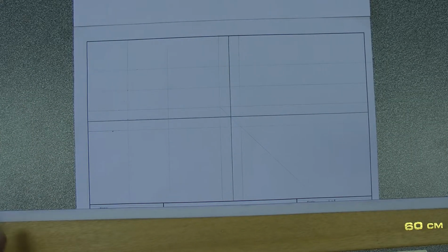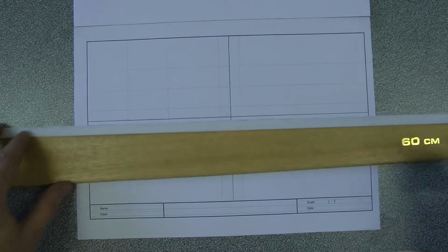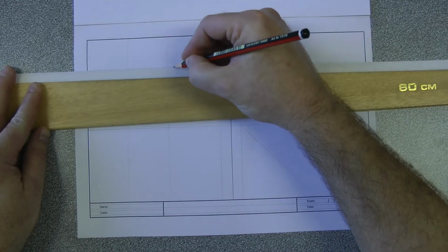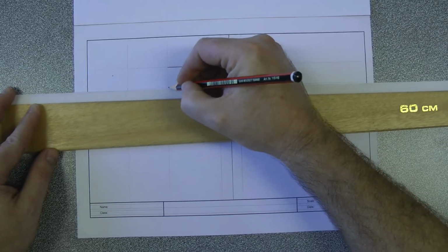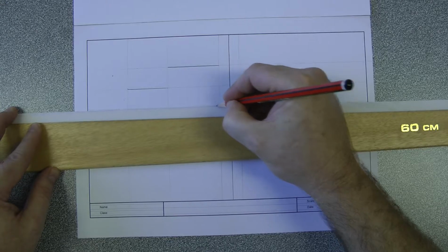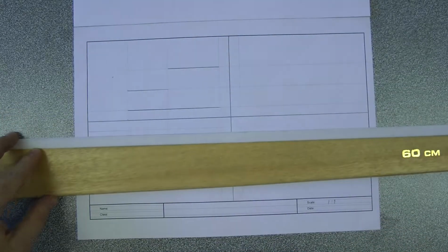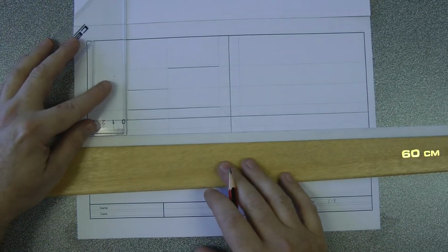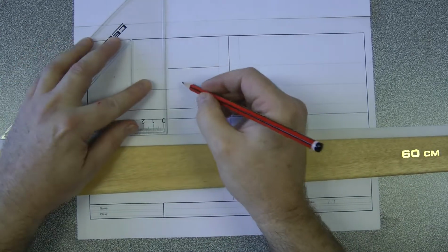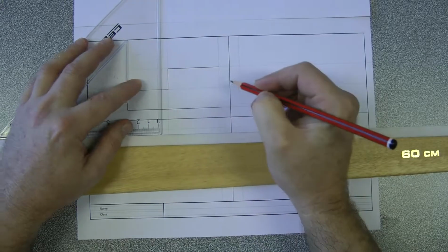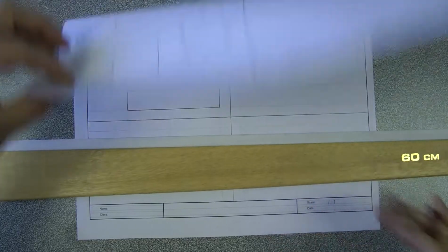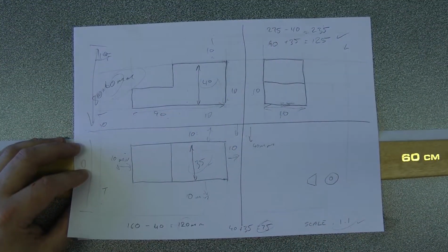Now I have enough information there to do my front view. I'm going to do all the horizontal lines first because it's a little easier, but I'm basically going to connect the points that have a surface attached to them. So those are my 3 horizontal lines. I'm going to bring up my set square, and I'm going to draw that and that one there. And that's my front view. And if you remember, that's what we drew in the first place.